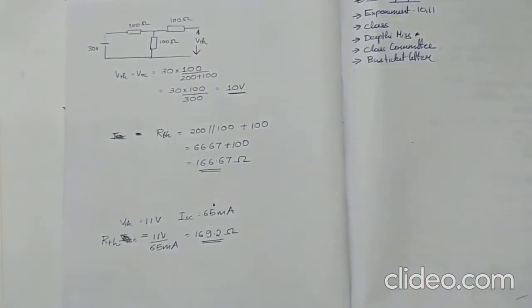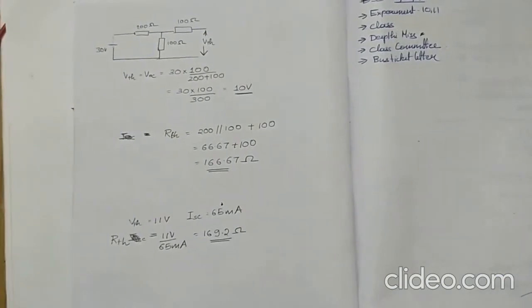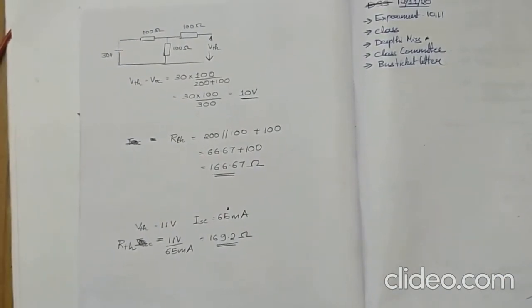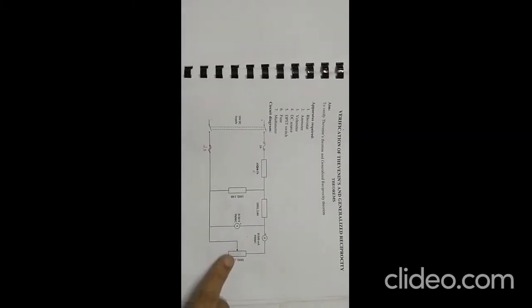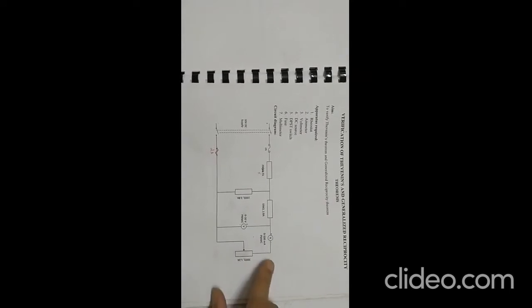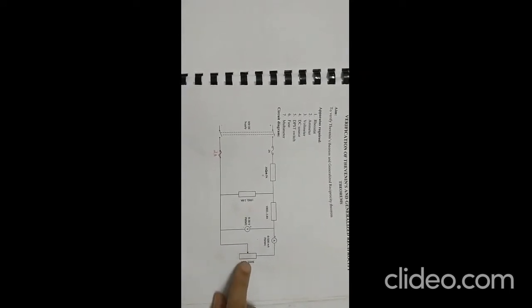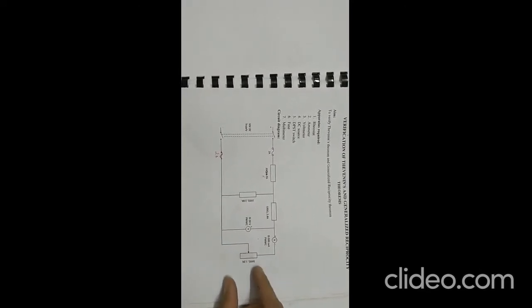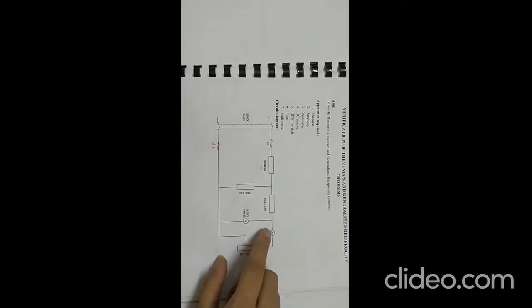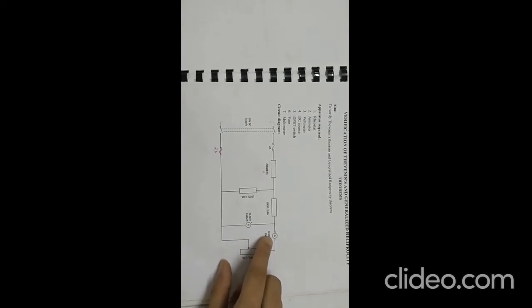Now we will connect the load onto this experiment and find different values of current and verify this. We will be wiring up the circuit to find the load current through the load, and we will be varying the load position to different values of 100, 300 and 500 ohm, and then we will find the load current using an ammeter connected in the circuit.